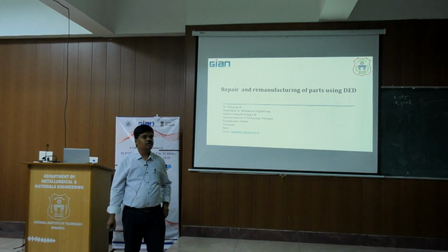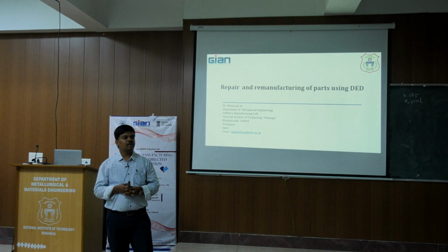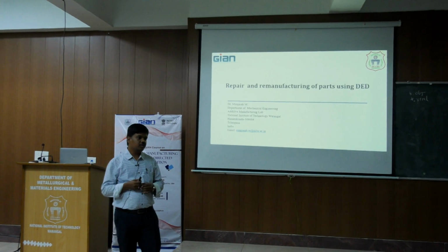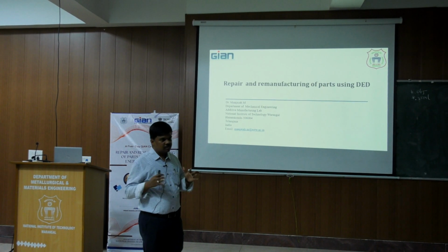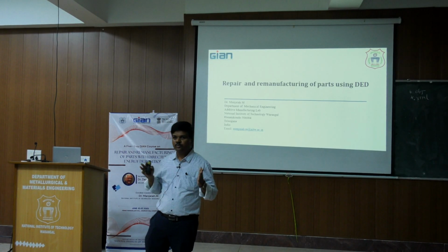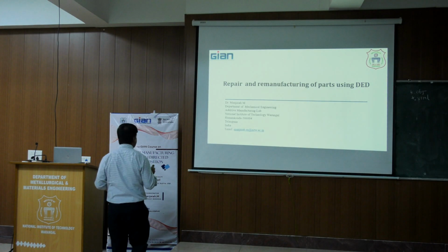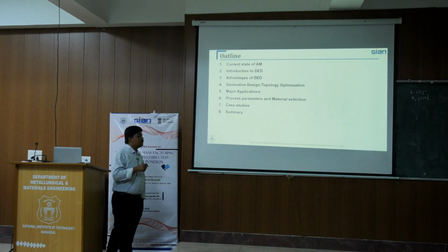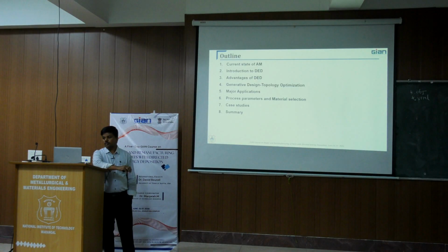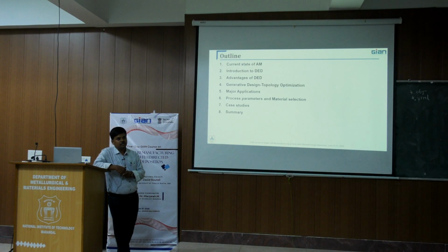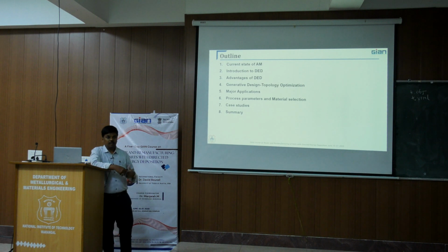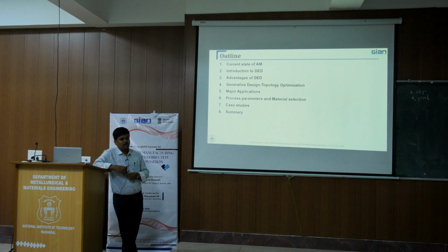We have done work with respect to the repair and remanufacturing of parts using the direct energy deposition process. We have also done some topological optimization for aerospace brackets, knuckle joints and other aspects. This is the outline of what I am going to give you, a brief of what work we have done, how we can make use of DED for repair, and what kinds of components we can repair and what kinds we cannot.